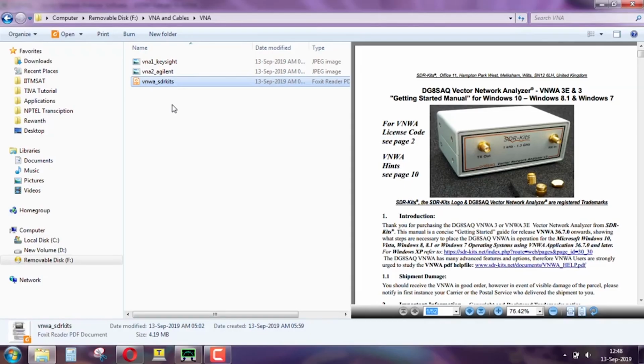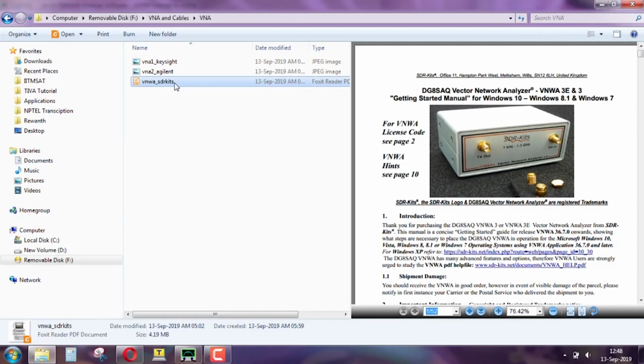Nowadays, we are getting something of slightly lower specs, but which I think really suits studies in universities, which are these mini vector network analyzers. So, this is a mini vector network analyzer. All it does is take in some input. It has a transmitter which sends out, which is your source in our transmission line course, and it has a port for receiving the data. So, it has a receiver, and then some processing, and then it connects to your computer, and it has its own dedicated software to show us what is going on. This is all it is.